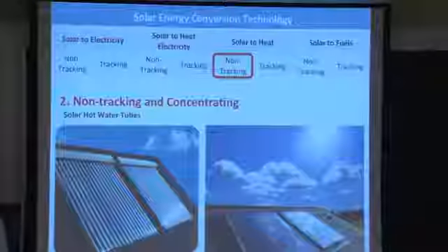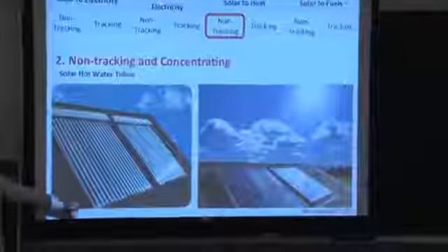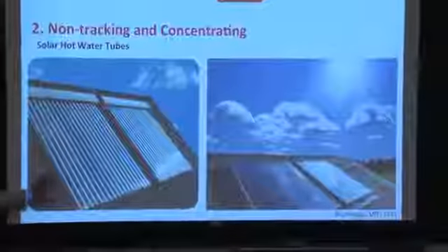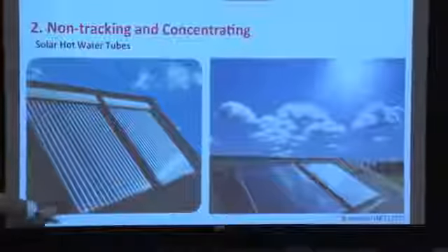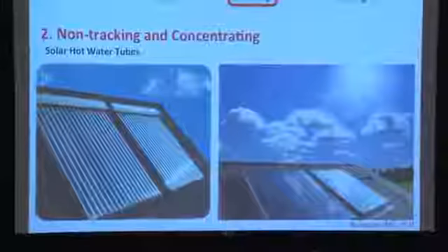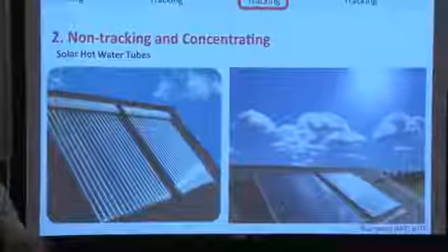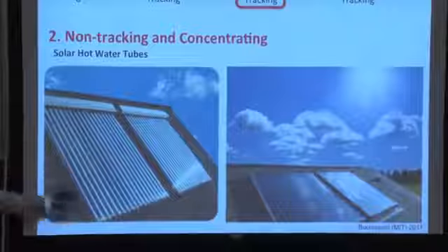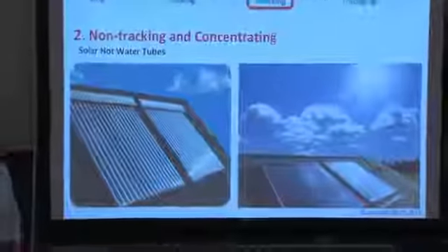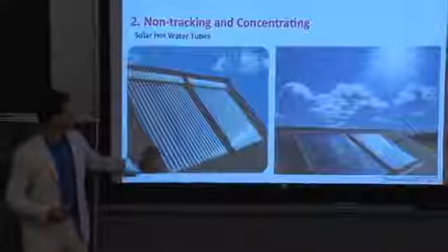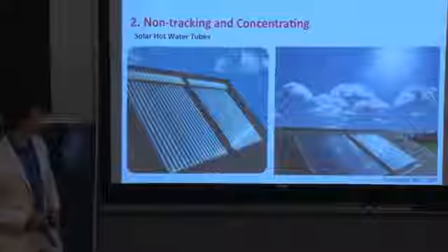And the fancier versions that are really marvels of engineering, these materials all have to be coefficient of thermal expansion matched. Right? As it heats up, the glass tubing has to match the expansion of the metal around it. So it is quite a feat of engineering that they make these so well. And there are a few companies in Germany that really pioneered this effort right here.